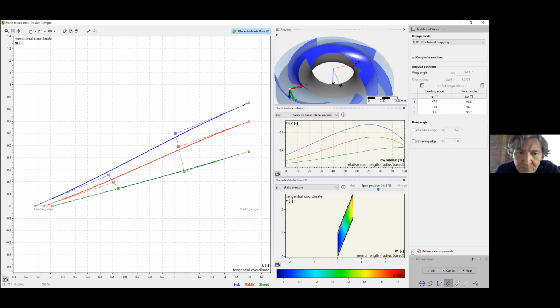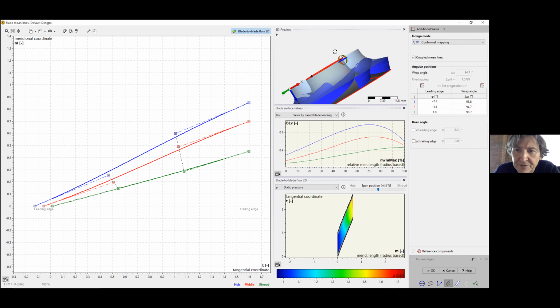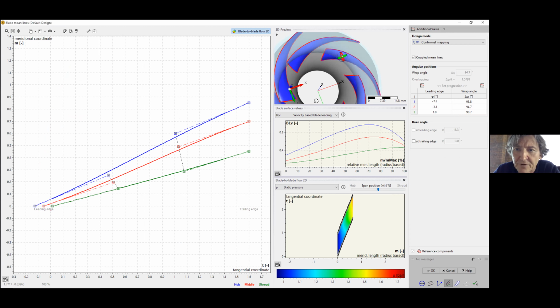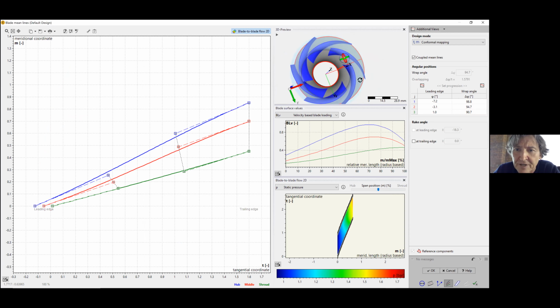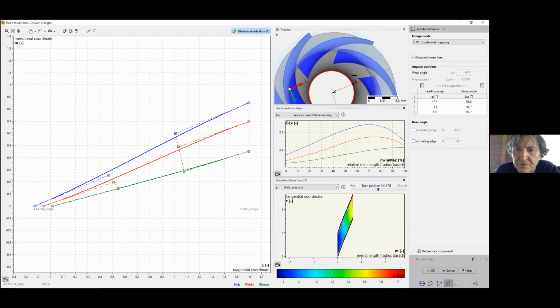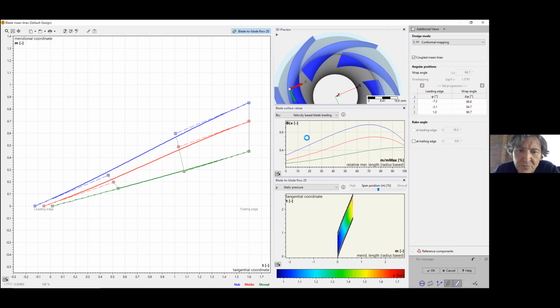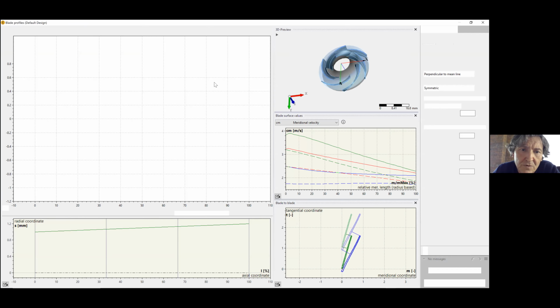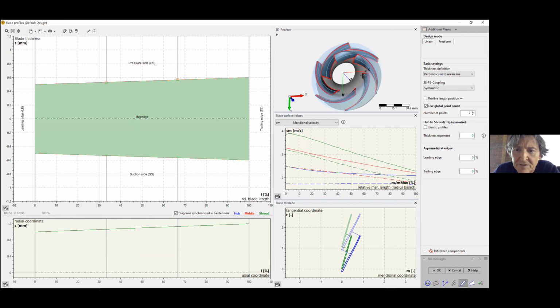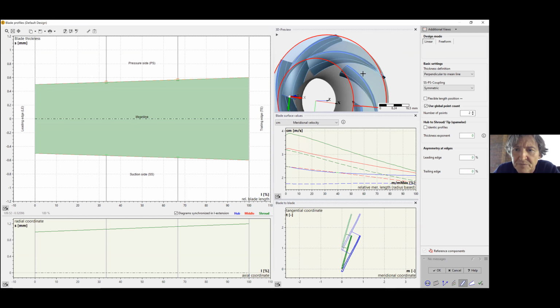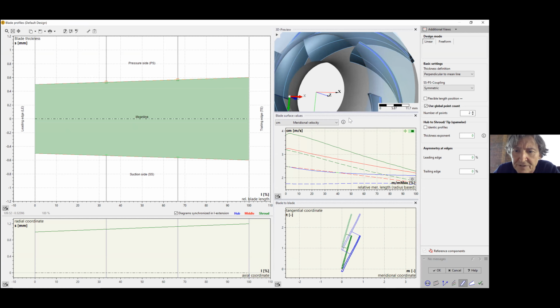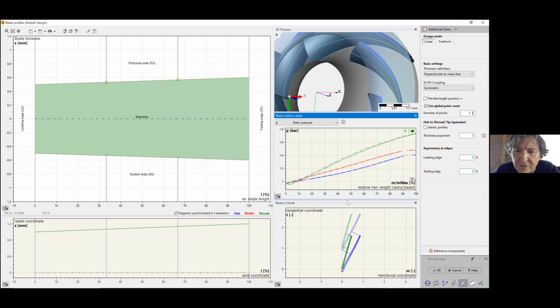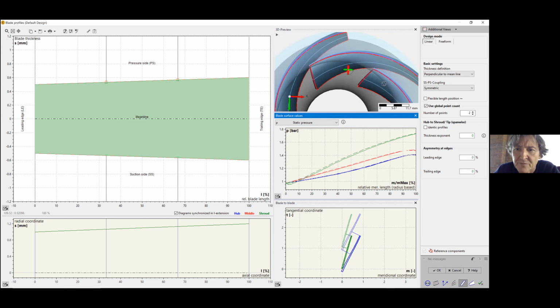And we already have now with our mean line design, which determines the curvature of the blade from the leading edge to the trailing edge, including the wrap angle, right? You see it here. Next would be blade thickness distribution. And for these types of pumps, I think we can keep this constant. Again, we see here we have the possibility to see different physical values like the static pressure or also the tangential coordinates, and always an immediate 3D preview.